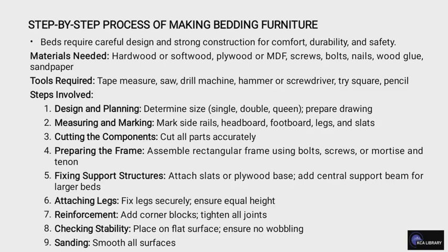For bedding furniture, a bed requires careful design and strong construction for comfort, durability, and safety. We also need the materials and the tools, as in the drawer. The steps include design and planning, and also measuring and marking. Then you cut the components, you prepare the frame, and you fix support structures, that is, you attach a slat or plywood base, and then you add a central support beam for a larger bed.